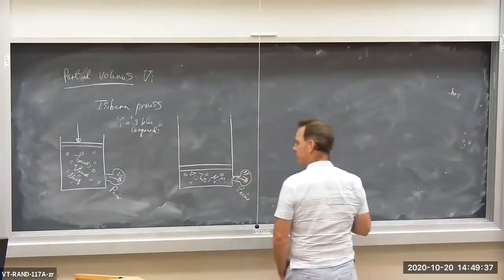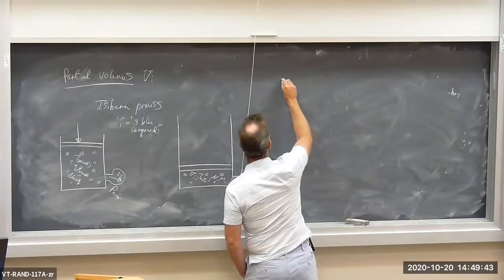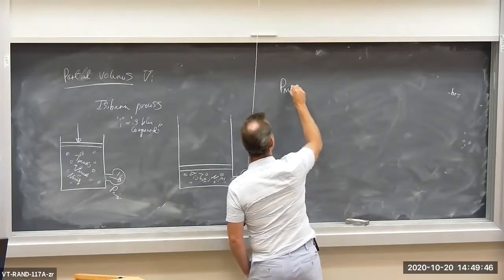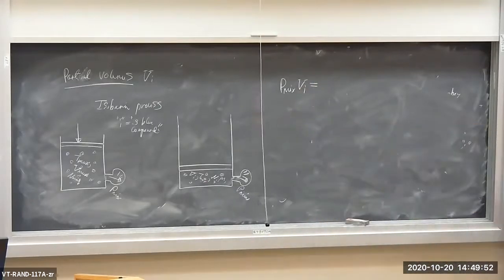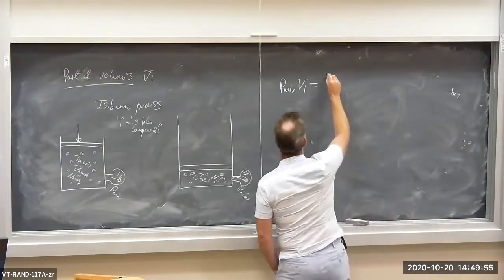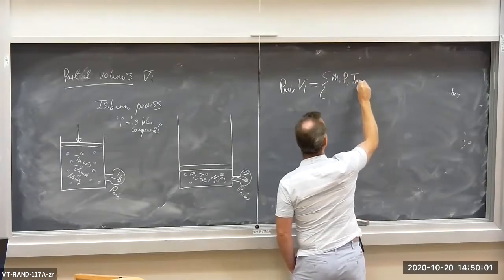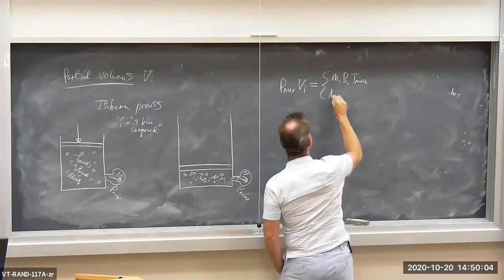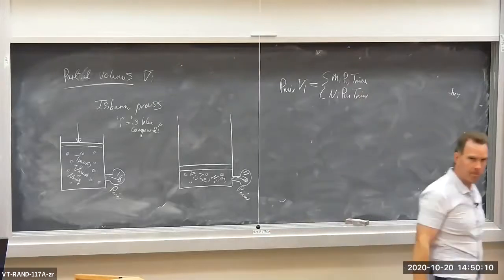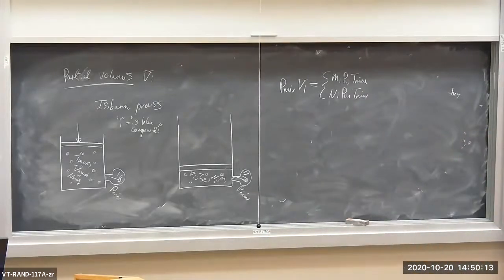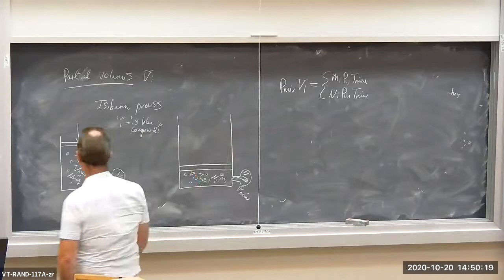And these temperatures, pressures, and mixture and component volumes are represented by the equation as follows. P mix times the component volume for component I is equal to, and I have two versions here, M_I R_I T mix, and N_I Ru T mix. So each component obeys the ideal gas law, and in this case, the V sub I refers to the component volume.